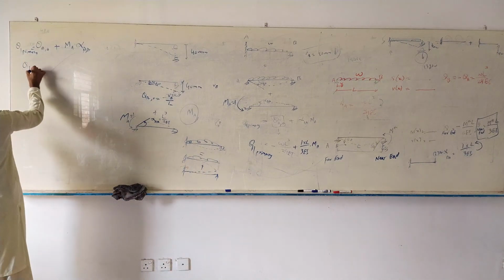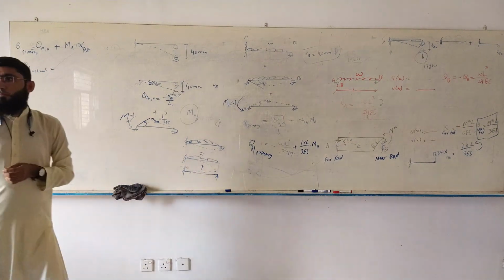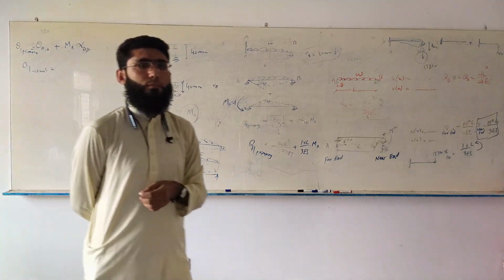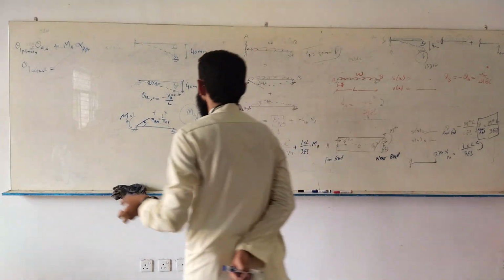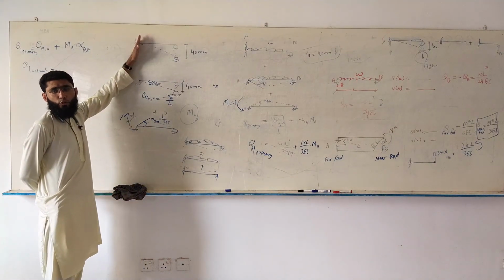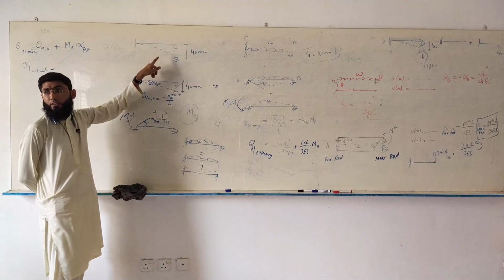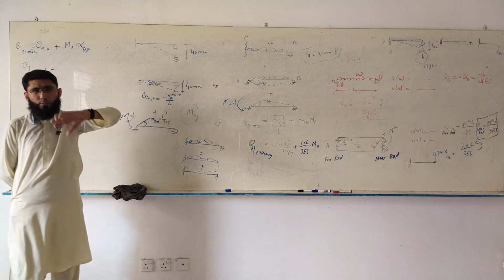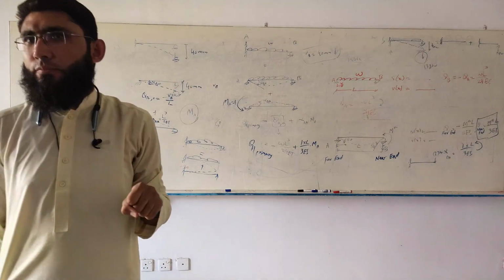What about theta actual? What is theta actual in the given beam? It is 0. The settlement is happening somewhere else. Although this is going down, due to fixity there's no rotation at this end. As soon as you get out of the fixed end, you will start seeing some rotation, but at the end where fixity is provided, it's going to be 0.